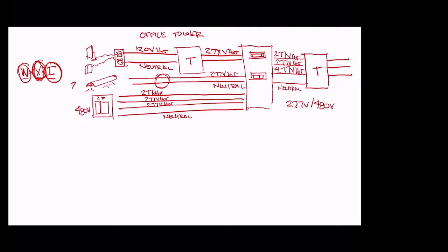And our lighting is going to be working on 277 volt, and our plug loads are still going to be 120 volt. All right. And it's important. I used to think this was bogus, but it's actually kind of important. People have told me over the years of doing these seminars that they buy an elevator, they specify an elevator, and they accidentally pick one that's a 208 volt elevator. Well, it won't work on 480 volts. So you have to know the difference. You have to know what flavor your particular building has.